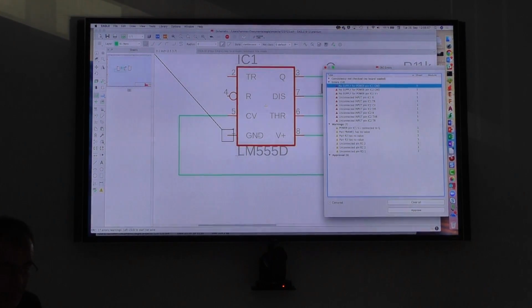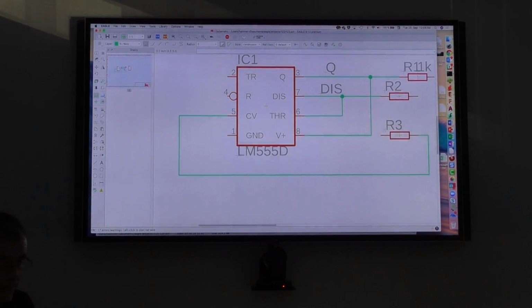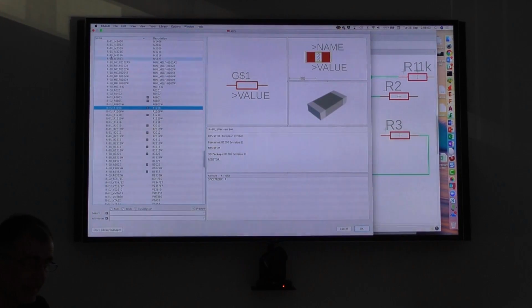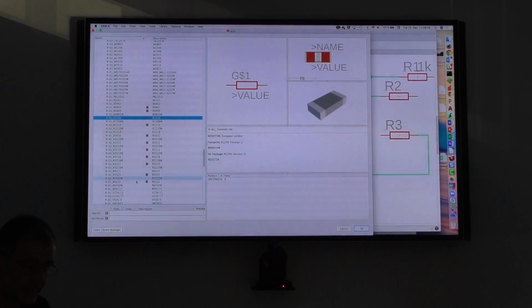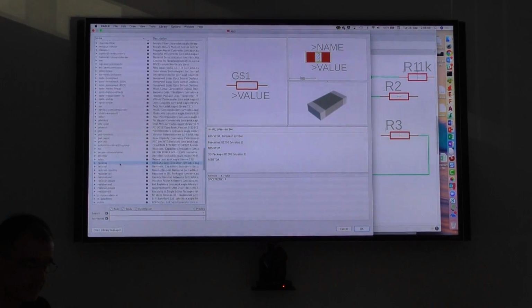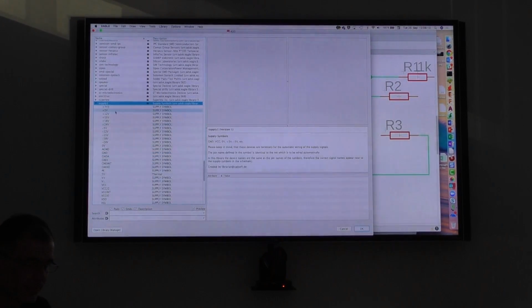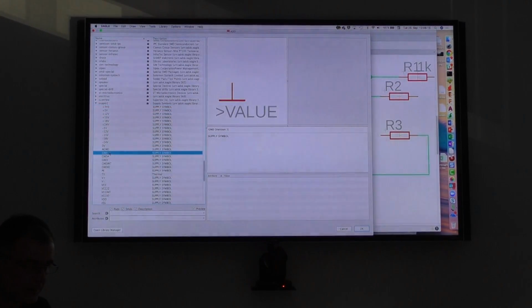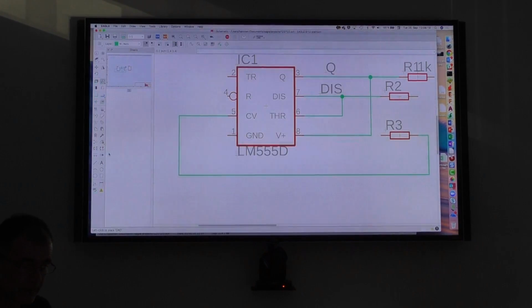And therefore we do a simple thing. The first thing is I go into the add command again, because I'm searching for a supply. And there are two libraries, it's very simple. It's supply 1 or supply 2, here and there. So they differ, it looks like, that's the ground. I take this one, I double click it, here it is. And I place it, I could directly place it on the pin.